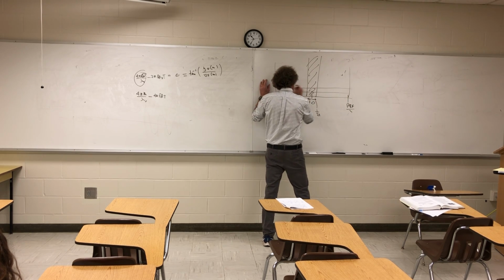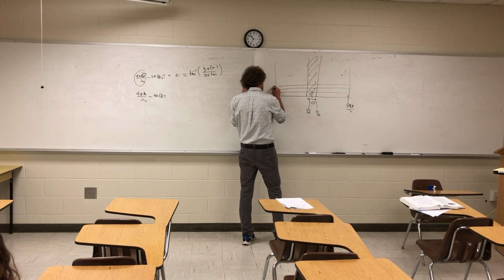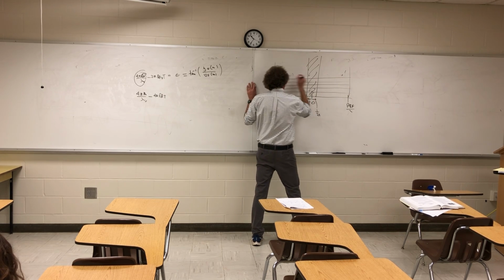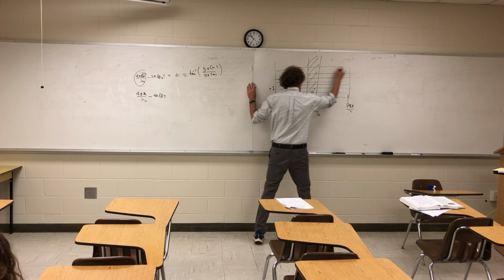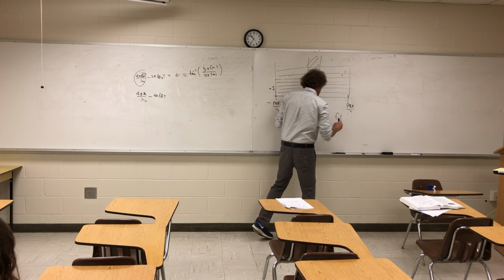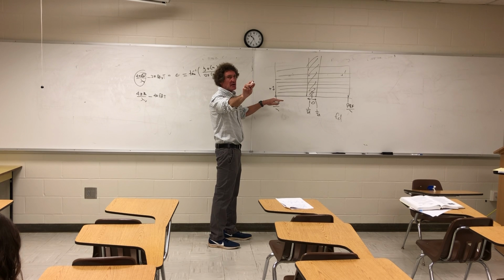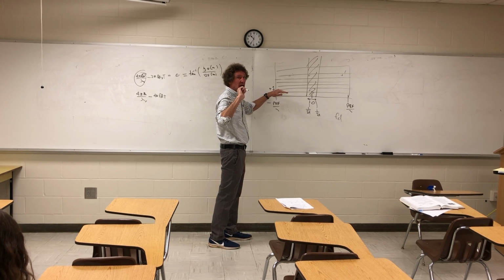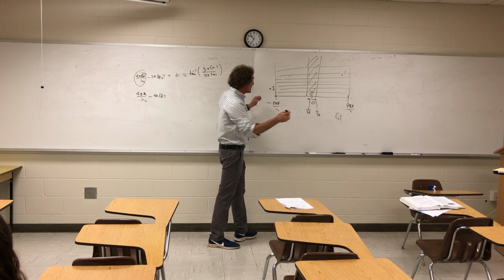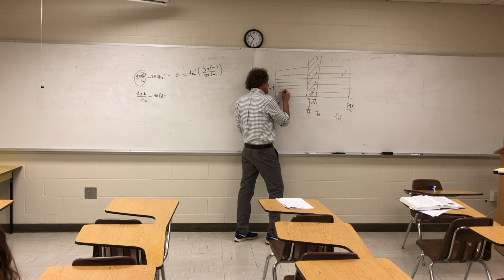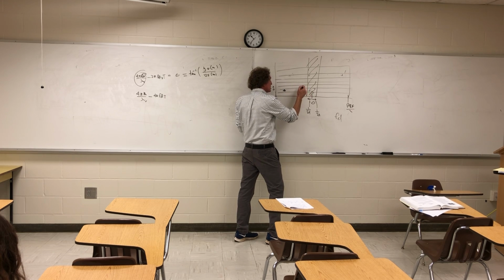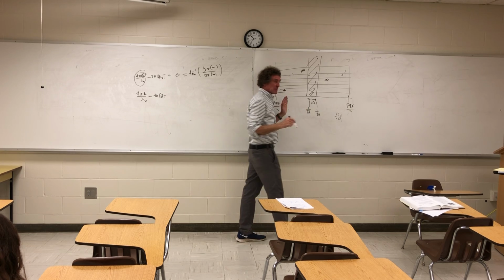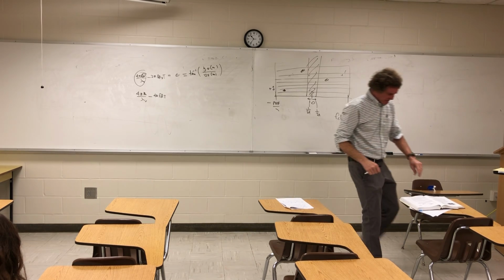They'll have a whole bunch of range, and each of these is associated with tau and time, and you can normalize that to range. They're going to have this, and this is the Doppler frequency. So as you go down, you send out information, it comes back. Then you extract to see if there's a Doppler shift in the size of the actual strength of the return. And if there is, what you'll see is you might have a target here, then you might have a target here, and a target here. And that's displayed in the book. I can find the page.